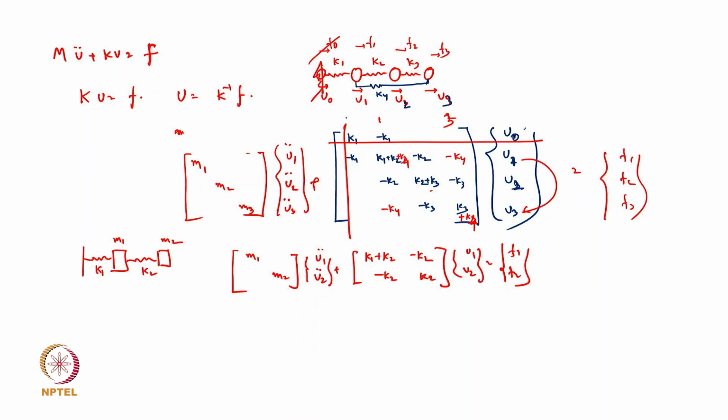Yes, then the point is where, what was the point? Yeah. So if we try to solve this equation of motion, just think that the forces are zero, like nothing is applying on that. We are trying to first calculate the natural frequency, and natural frequency we calculate for free vibration, not forced vibration. So free vibration means F1, F2 all become zero.